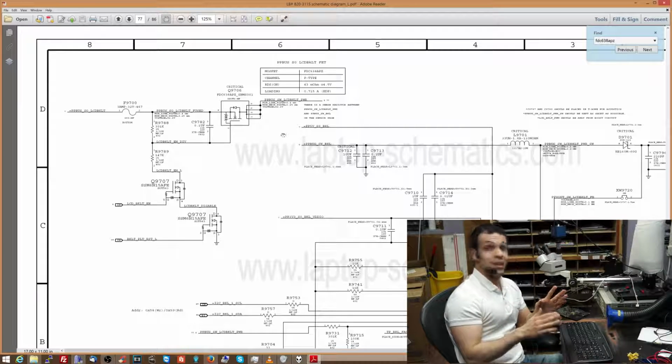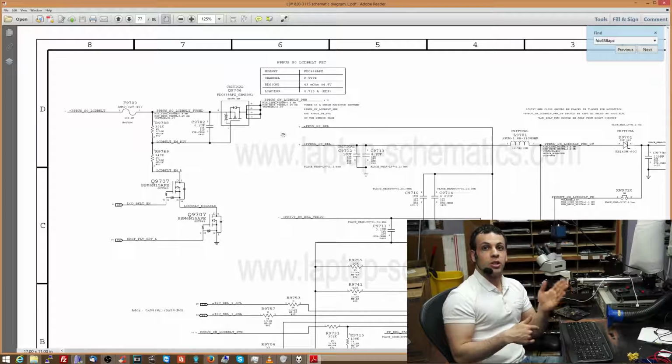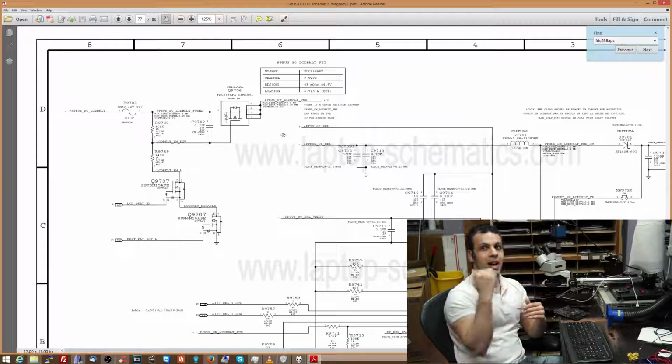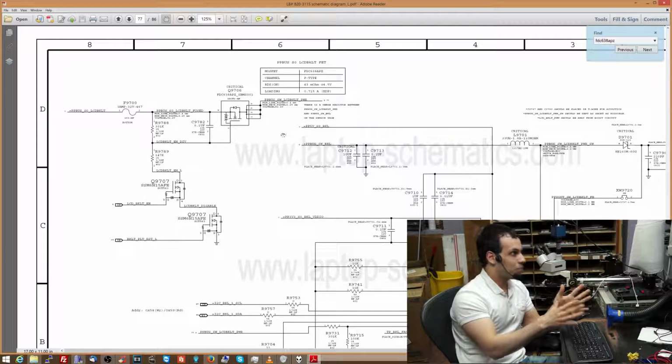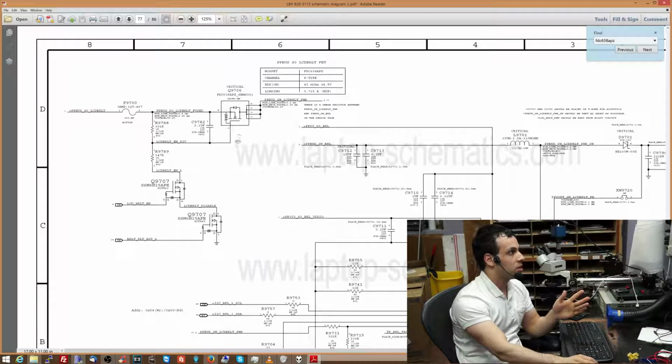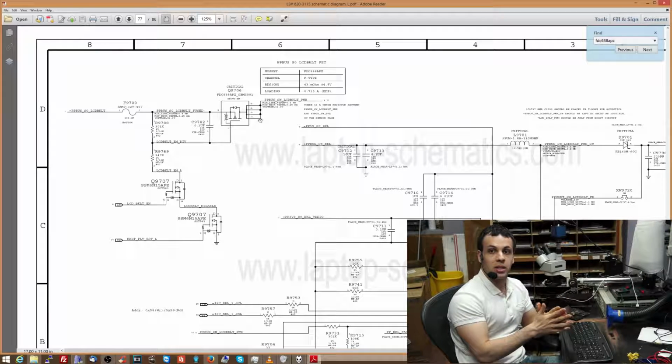Now, for the most part, when it comes to laptop circuitry or any of the circuitry I'm showing here, it's pretty much being used as either infinite resistance or 0 ohms. So the transistor is pretty much being used where it's either a wire or it doesn't exist. It's like it's blocking all power going through. It's pretty much being used as a switch. But the way this works, it's used as a variable resistor. It's used as a resistor whose value can change based on the signal that you send to the gate.